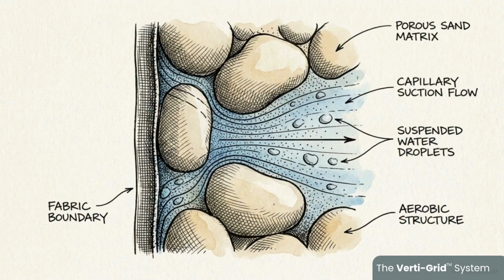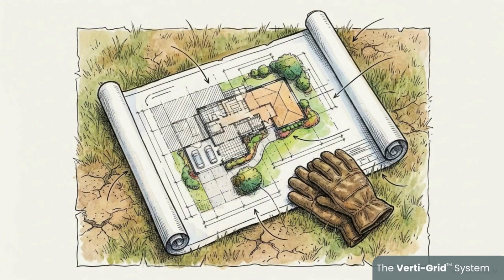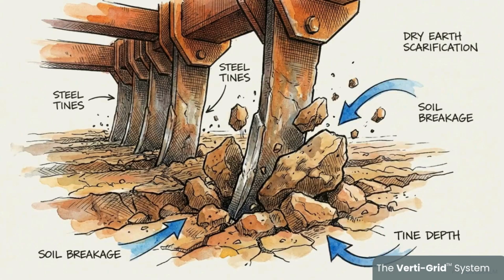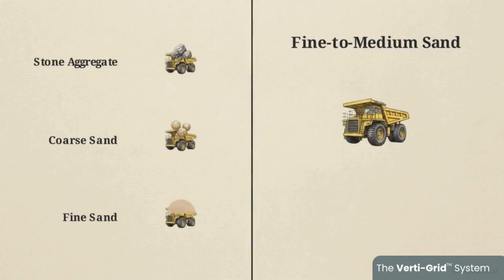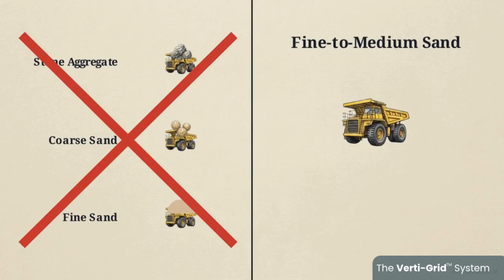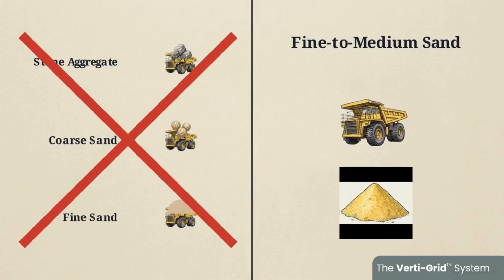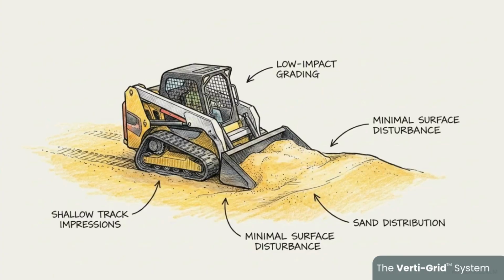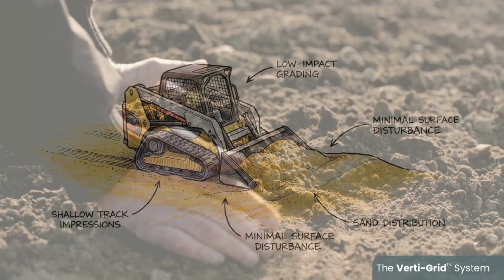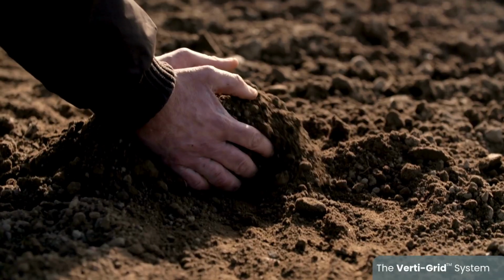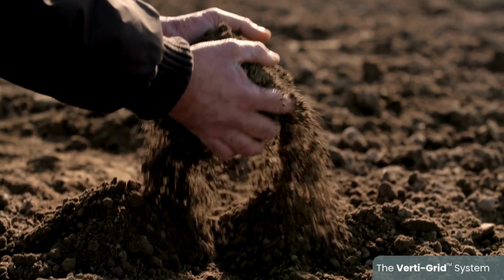The recommended construction procedure is to prepare the ground surface by roughing it up by methods used for existing mound construction, and then build the entire mound out of fine to medium sand with mild compaction using light grading equipment. The mound can actually be graded to the desired height and shaped to finished grade. Topsoil can even be placed before the Verti-Grid is installed if desired.